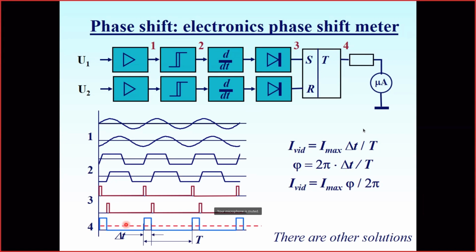And the digital device measures here either the trigger power supply voltage, and actually the trigger gives 1 output voltage, let's say 5 volts, or 0 when the trigger shows 0 on the output. Here it's important that this is a mechanical device. It has an inertia, and because of inertia, when we apply such short pulses, the mechanical device actually makes an average over these pulses. And if the pulse duration is very short, it has very small spikes, small pulses of current, and the average current will be small.